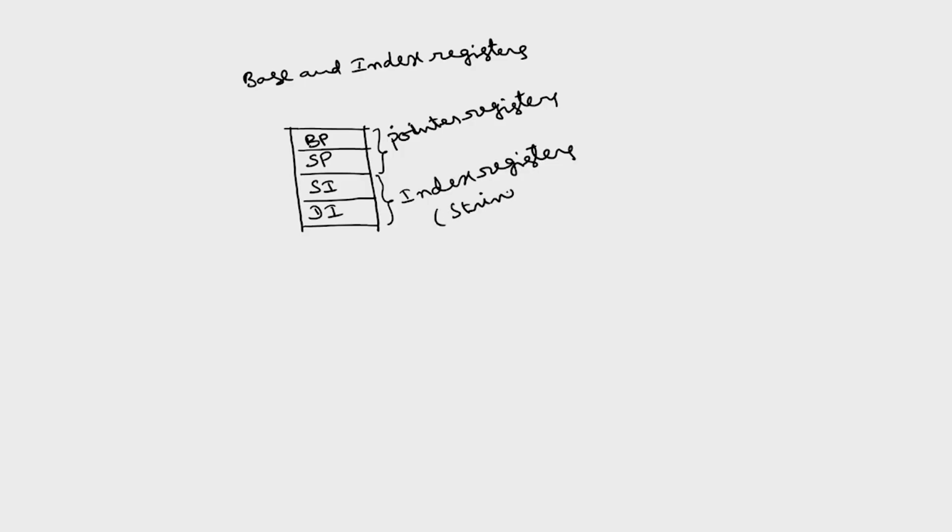I will discuss what is meant by string operations later. They are basically used in string operations and for address calculation, in case of physical address calculation or stack related work. The stack pointer is the same as the 8085 stack pointer. The stack pointer always addresses the stack top. I will discuss the details while discussing this architecture as well as the addressing modes and the instructions. And there are some other registers called segment registers.